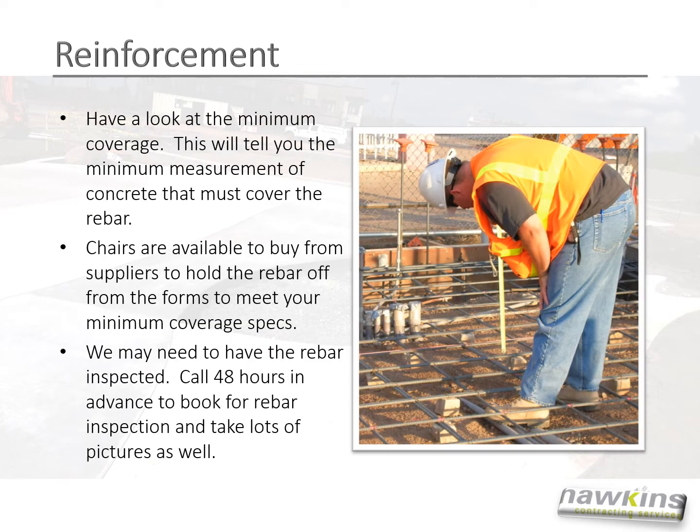Have a look at the minimum coverage. This will tell you the minimum measurement of concrete that must cover the rebar. Chairs are available to buy from suppliers to hold the rebar off from the forms to meet your minimum coverage specs. We may need to have the rebar inspected. Call 48 hours in advance to book for rebar inspection and take lots of pictures as well.